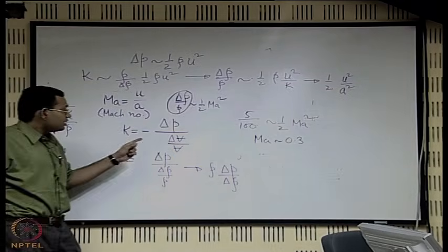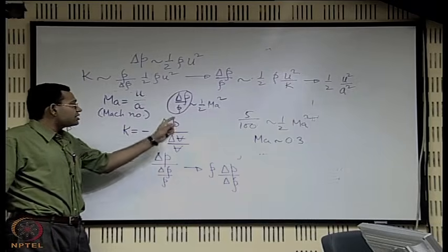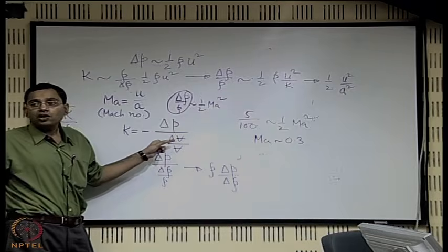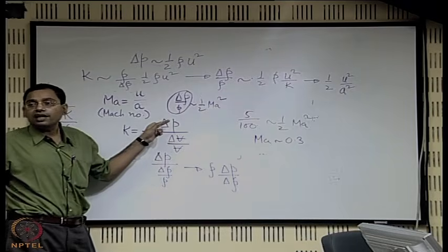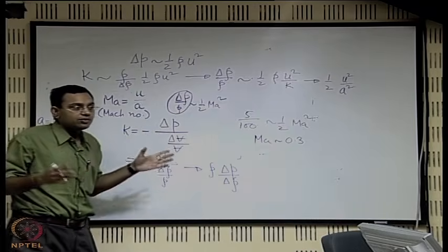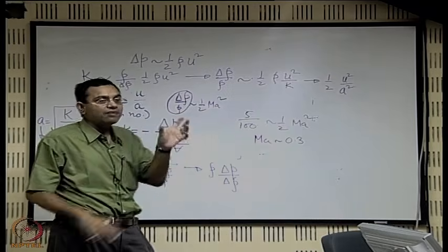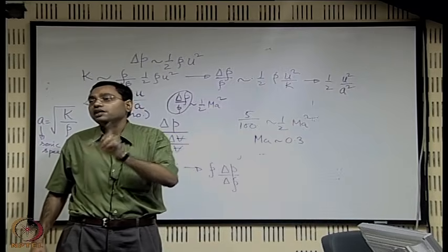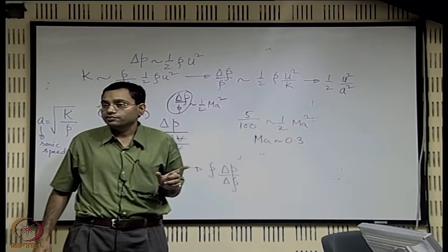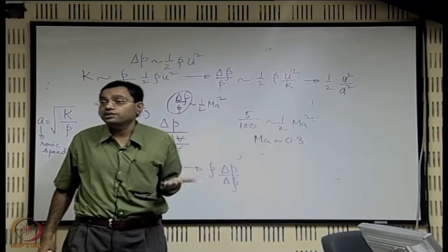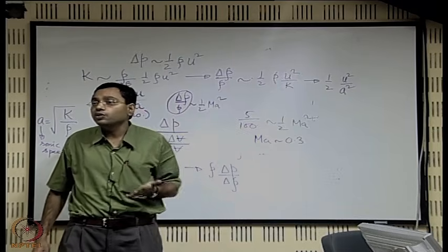So incompressible flow means that there is no volumetric strain of the fluid element, there is no change in volume. But you cannot directly always relate it with this definition, because the change in volume may not always be due to change in pressure directly, it may be because of something else also. I mean, there are reasons for which you might have a change in volume of a fluid element not because of the change in density due to change in pressure, but maybe because of change in density due to change in temperature, not directly due to pressure.